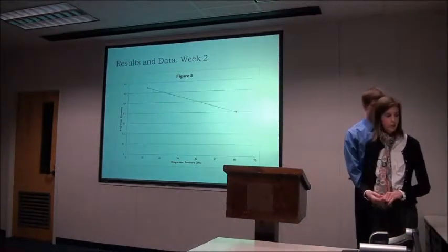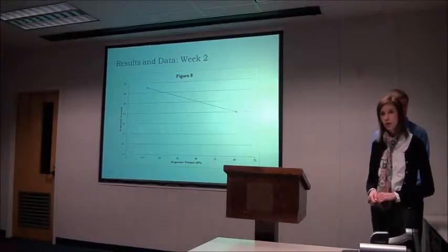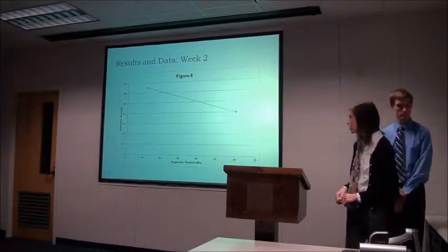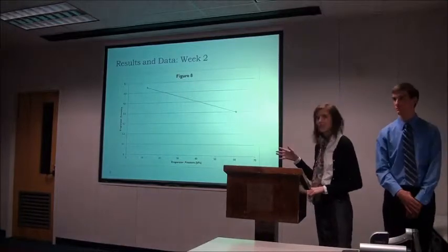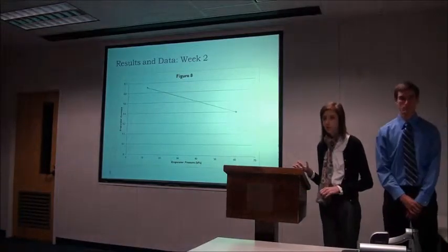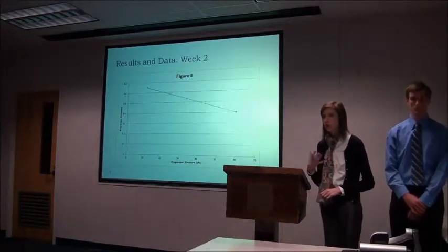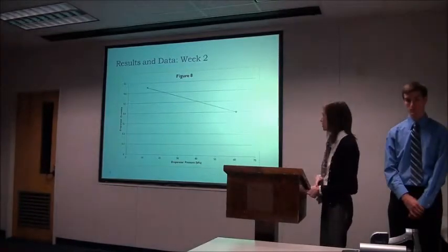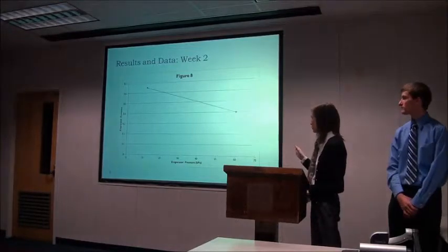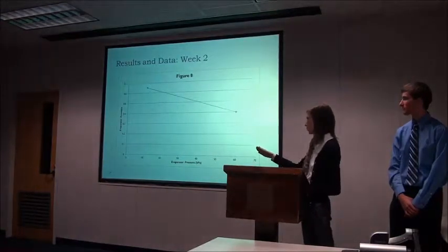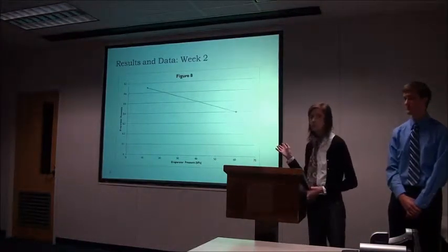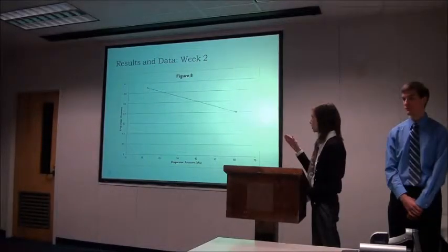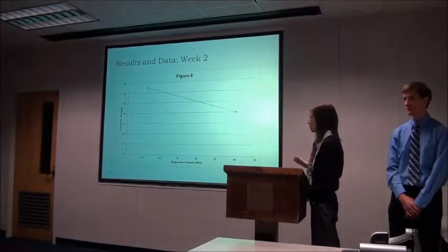Just as a refresher, week 2 was where we had the system under vacuum pressure. We can see from the graph, and again, there were only 2 trials run for each scenario, so possibly we could have seen a better trend if we had time to perform more trials. But from our 2 data points, we can see that as the evaporator pressure is increased, or under less of a vacuum, our overall economy also decreases.